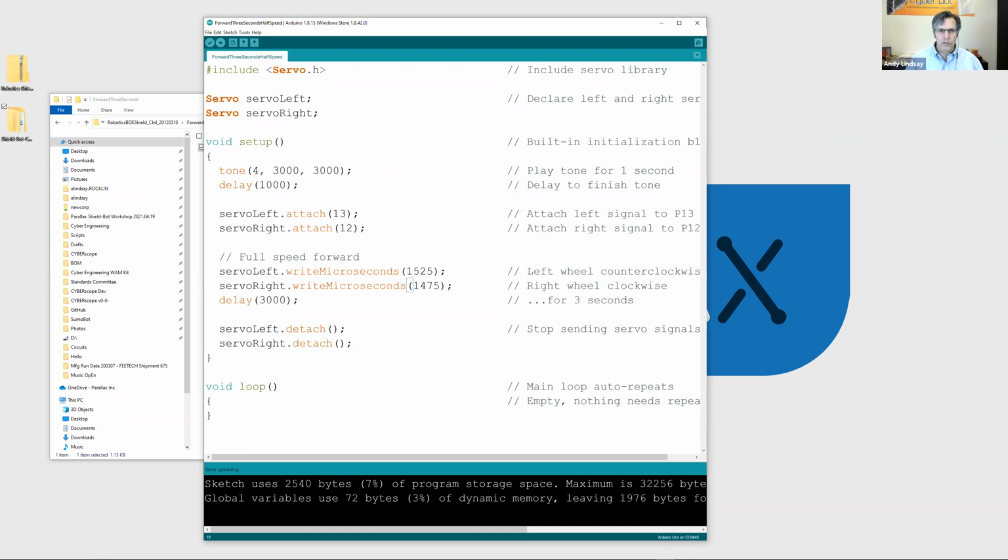And whoever was wrestling with that, if you try new batteries and it fixed everything, great. Otherwise, check to make sure that the battery cable is firmly plugged into the Arduino. If it's just partially plugged in, it might be hanging on and behaving like it's plugged in, but not supplying the power. I was the guilty party, and a fresh set of batteries took care of it. Oh, excellent.